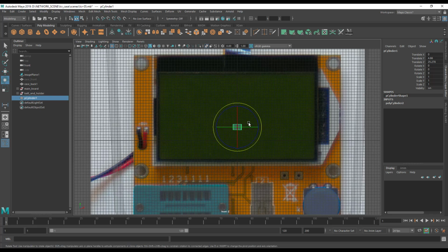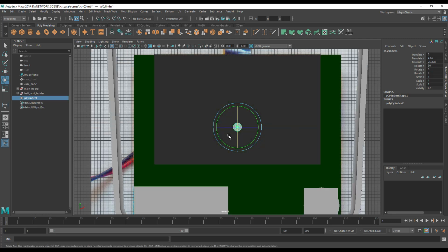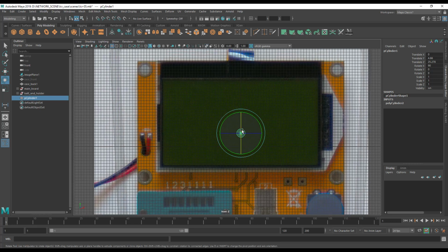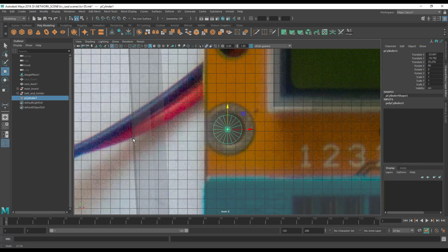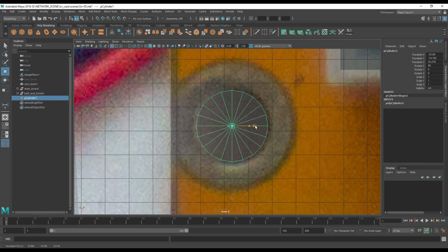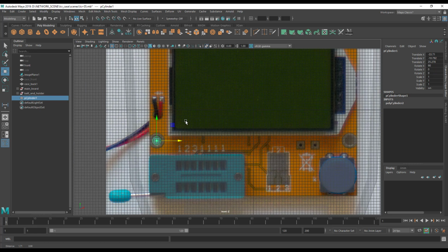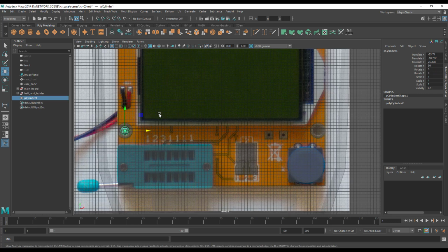Right, let's rotate it round, hit E and J and flip it 90. Aha! I'm on X-ray. That's why I was a little confused at the view I was getting. Alright, but we know this is 3mm now, so we can move it down to here and see. We hit F to line up precisely. And we can see that this was obviously designed as a 3mm hole. There's a little leeway either side, and that's perfectly fine.